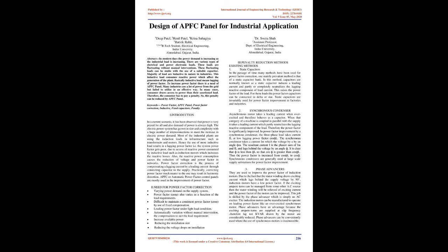The majority of loads in industries are inductive in nature. This inductive load consumes reactive power, which affects the generation of the plant. Basically, inductive load means lagging of power factor. To increase power factor there is a need for an APFC panel.